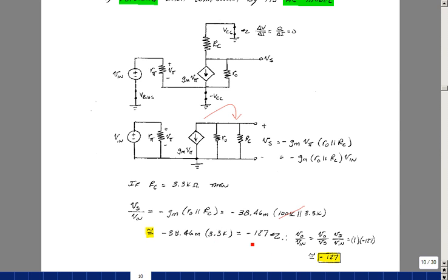we're looking at about a voltage gain of minus 127. So we'll get a phase inversion. That's going to multiply the gain of 1 in the power amplifier. Overall gain would be around 127. So we get large voltage gain, and then of course a very, very large current gain, really added on to the current gain of this stage too.